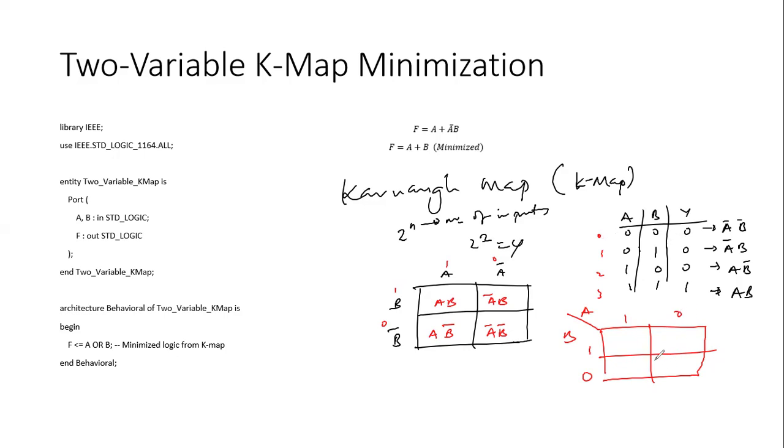So we're going to plot, this will be the 0 box. Then the 1 box will be 0 1. So this will be the 1 box. Then 1 0, this will be the 2 box. And then 1 1, so this will be 3. Okay, so depending on your reference text, you may see the K-map represented in this format where we have numbers assigned to it, where this is 0, 1, 2, 3, depending on the number of variables. Then it could be this format, it could be this format. So if we have to plot this, then we know we are going to plot it here.